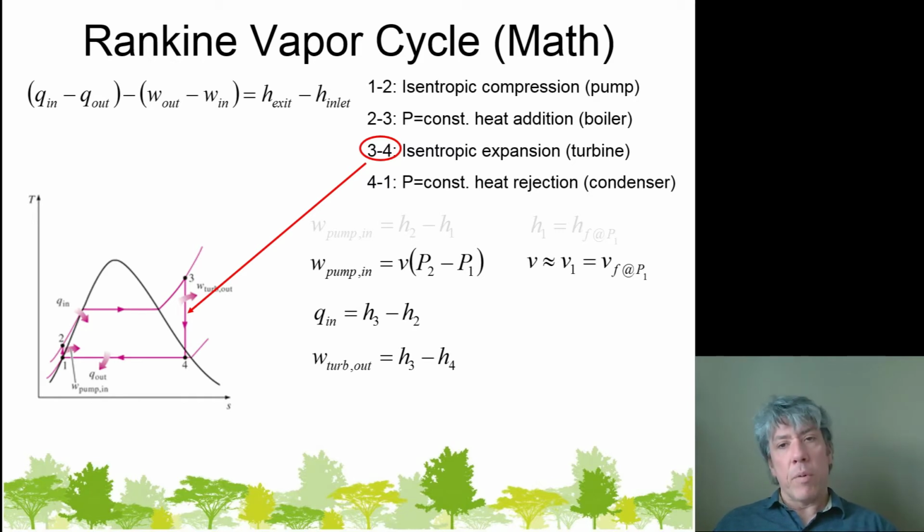And then the enthalpy in state 1 is just the enthalpy of saturated liquid at the condenser pressure. So H1 is known, the pump work is known, and so we would calculate H2 as the pump work plus H1. Now you'll see that in an example problem, but you might want to rearrange the equation that you see there sort of ghosted out and just write H2 equals H1 plus the pump work, because that's the form of the equation that would be really useful, and it's really useful when we're dealing with the energy balance on the boiler, because that's where we really need H2. Okay.